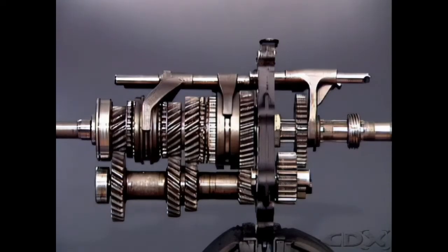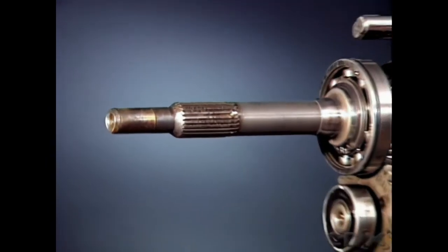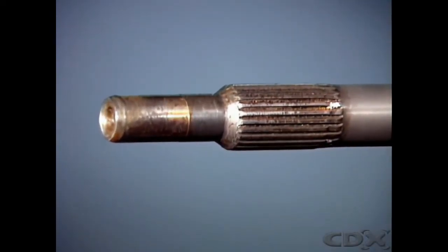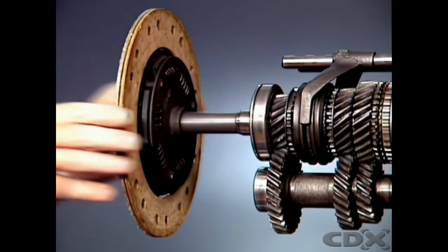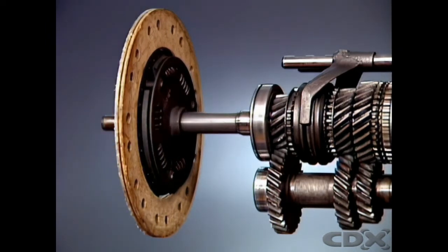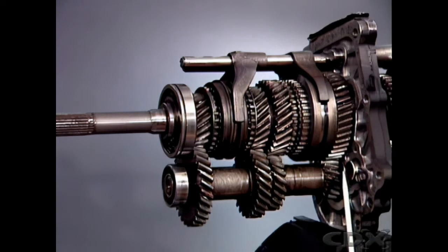In a manual transmission for a rear-wheel drive vehicle, the gear train is built up on 3 shafts. The input shaft extends from the front of the transmission. An external parallel spline section engages with internal splines on the clutch-driven plate. A main drive gear is an integral part of the shaft. It meshes constantly with a mating gear on a counter shaft, which has a number of gears formed on it.